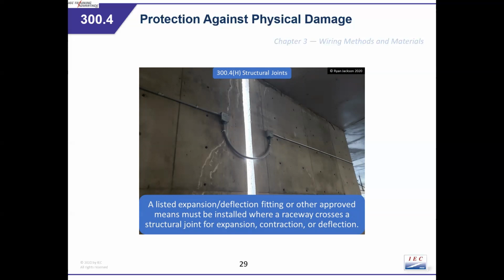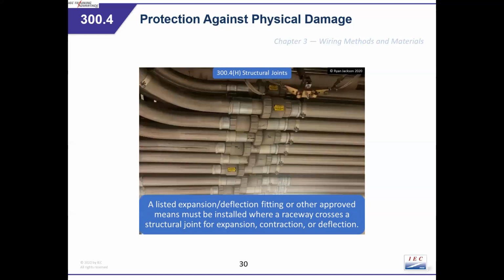You know, most building sizes, this is not an issue. If you get into really large warehouses, this becomes an actual issue. There's a couple methods there. They actually make a fitting that would go between those two boxes. That's a straight piece of raceway and it slides in and out of itself. And then they accomplished it by using seal tight, flex, something like that.